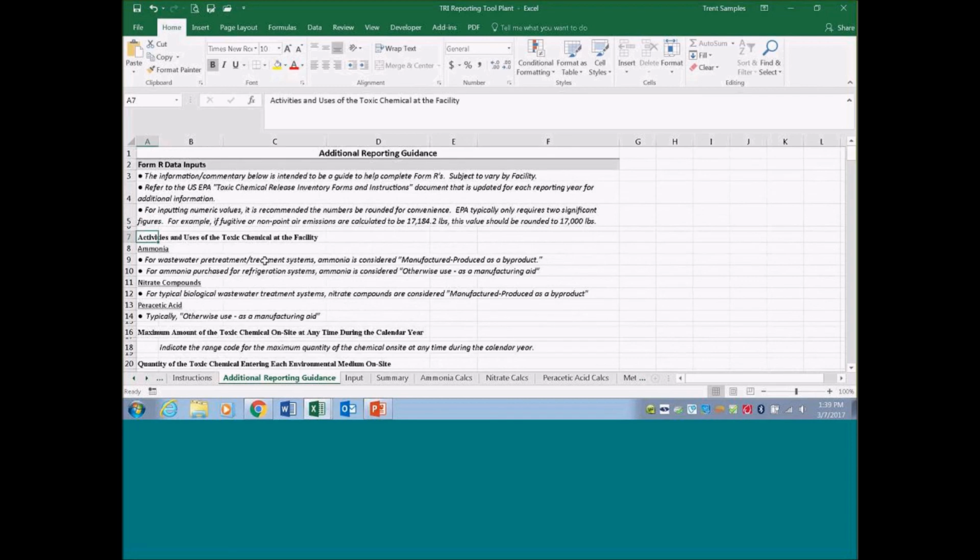Well, you also need to consider your type of treatment system. In the case of this SBR, sometimes there can be an anoxic stage or settle stage, so you need to take into account, does my treatment system allow potential removal of nitrates? And if it does, then you probably need to consider the removal performance of nitrates.